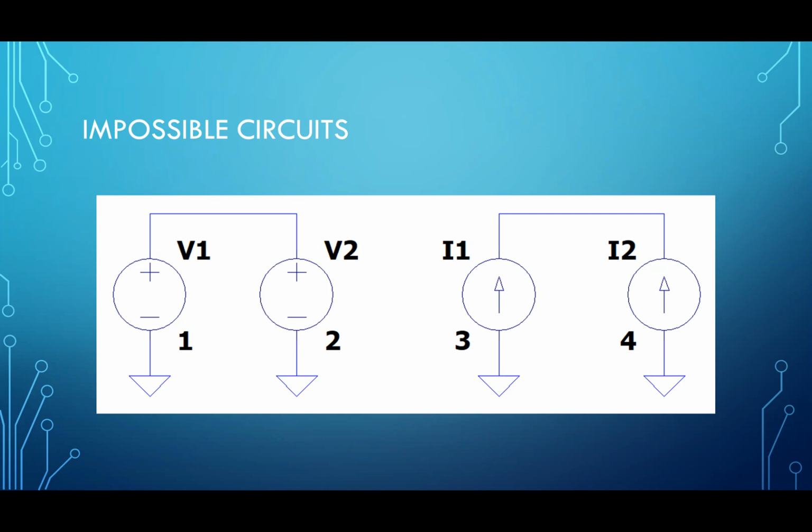The simulator actually would not complain about that. The simulator would just give you an extremely large value of voltage, say, 10 to the power of 308 volts or something like that, which is just an artifact of the way that the simulator solves circuits. The simulator uses modified nodal analysis, which means that it's using equations of Kirchhoff's current law, and as such, it views the circuit on the left as being overdefined, and the circuit on the right just creates these ridiculous numerical values.